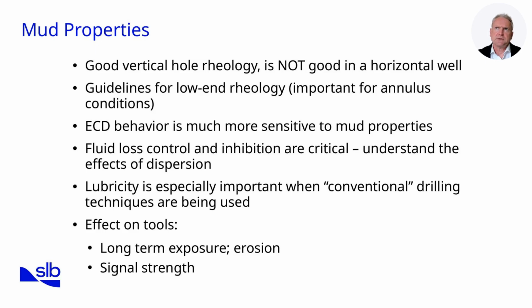Lubricity also plays a bigger role in ERD, because we often rely on conventional drilling methods across extended intervals. Finally, we must consider long-term effects on tools, such as erosion from extended exposure and reduced signal strength in MWD/LWD systems. Now that we've set the foundation with fluids, let's move into drilling efficiency strategies and parameters.